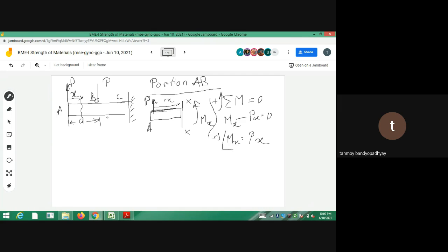So you can see that this is a y is equal to mx type equation. So you can see that the moment actually varies with the distance x. It is not constant from A to B. It actually varies with the distance x from A. So if I write that down, at x is equal to 0, which point am I at? I am at the point A. So M_A is equal to 0. So at the point A, the moment is always 0.